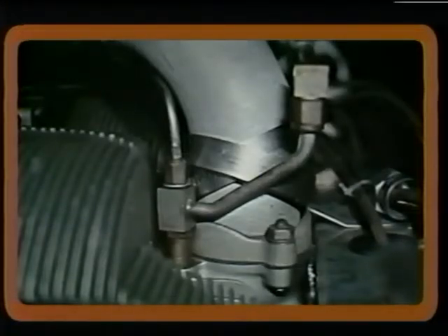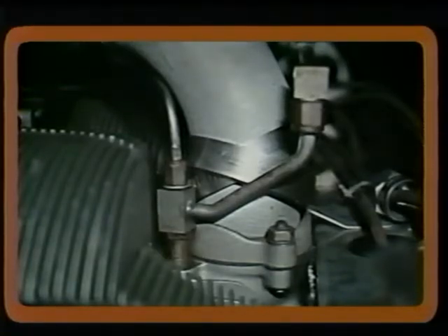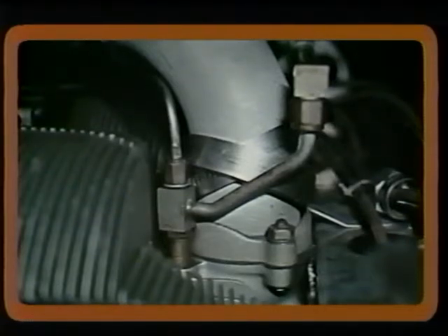Today's turbocharged engines, because of their high power output and efficiency, almost always use fuel injection systems to perform fuel metering. And because these engines often have manifold pressures higher than the ambient air pressure, special provisions must be made to keep the fuel from being blown out of the nozzle through the air bleed hole. To prevent this, these nozzles are usually shrouded, with the shroud connected to the turbocharger discharge pressure.